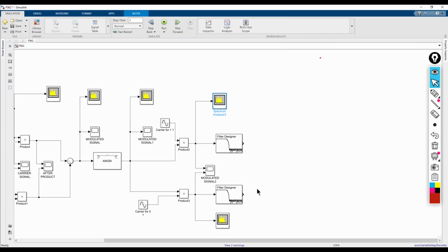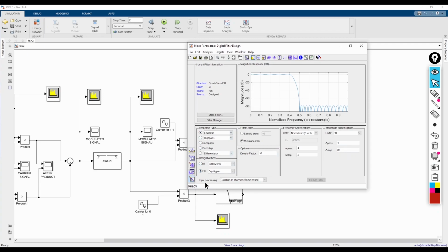Okay, so let's go to our filter designer again. It will be a low pass filter and an FIR method, and here it will be our frequency base. The sampling frequency should be the same as our sampling frequency, which was 5000. And this is Fpass and Fstop. Fpass we decided about 20, and Fstop will be 50 hertz.